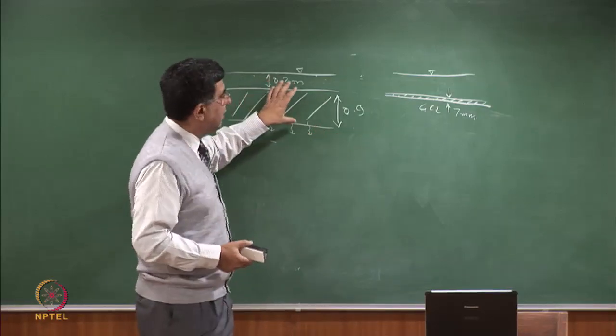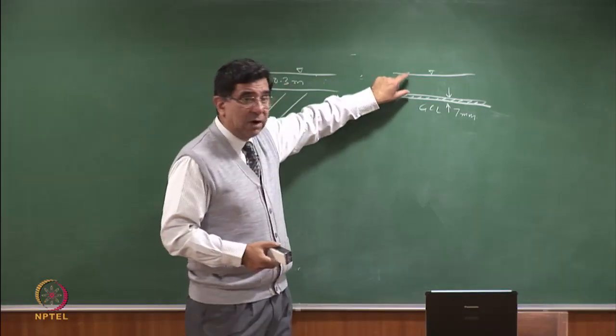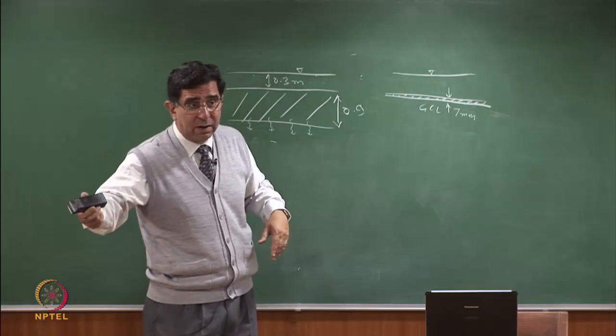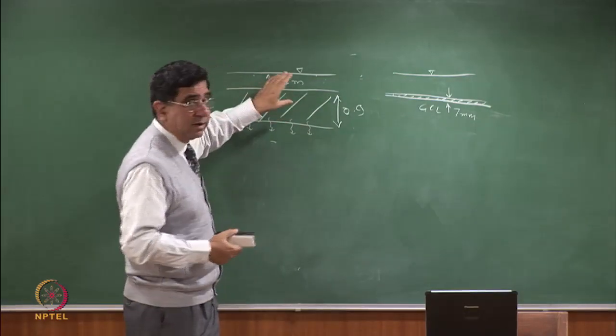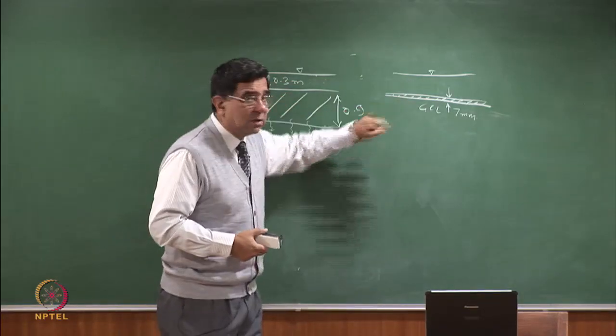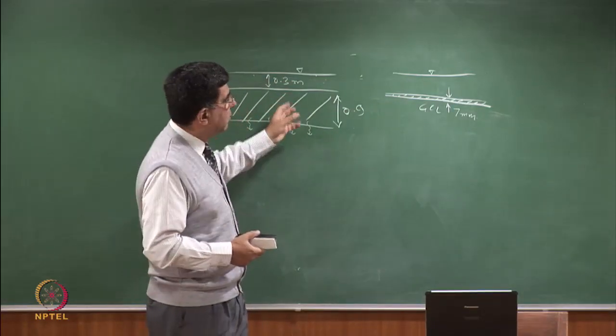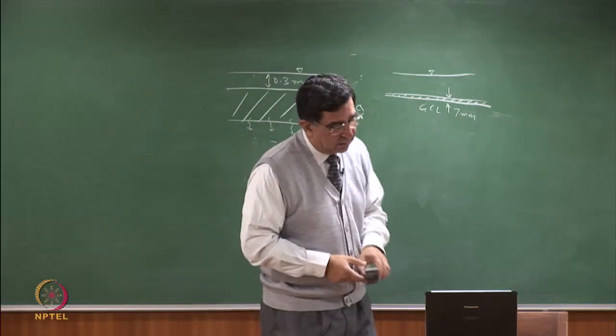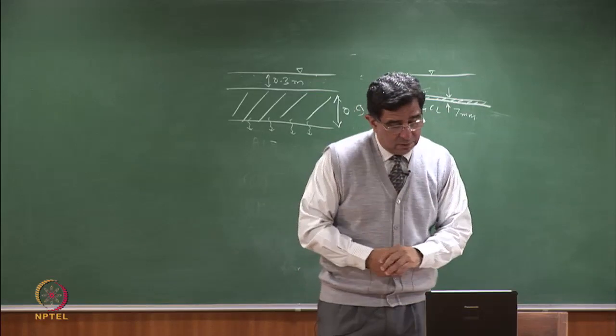So please understand, once again, your hydraulic gradient is going to be very high here. Just like you're at 201, you're going to have a high hydraulic gradient here. But the permeability of this is much lower. And we'll do this comparison in terms of the advective mass flux.